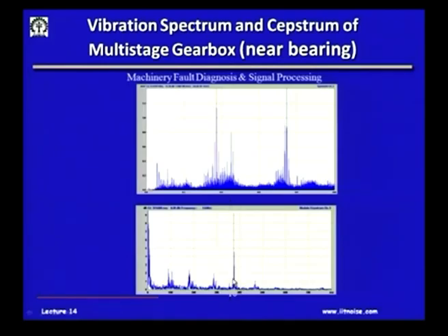So, if I come to the second plot here, they are all in time domain, and the corresponding frequency will be shown. You will know this corresponds to a particular rotational shaft of the gear, and we will know its frequency content. From this we will know that this has a high amplitude, meaning this is the strongest sideband, and that is what Cepstrum helps us in.